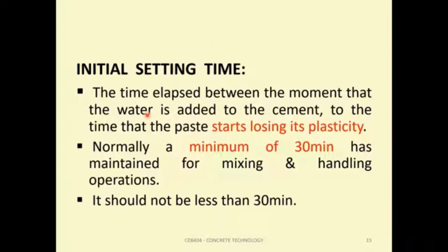Initial setting time is the time elapsed between the moment we add the water to the cement to the time the paste starts losing its plasticity. Normally, a minimum of 30 minutes is maintained for mixing and handling operations. So it should not be less than 30 minutes.